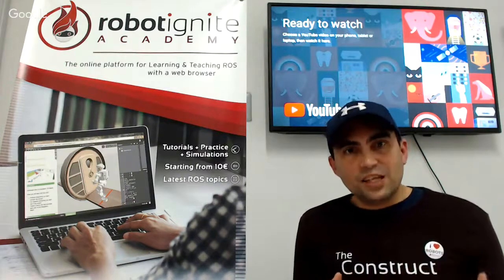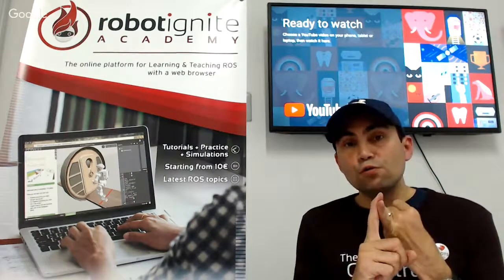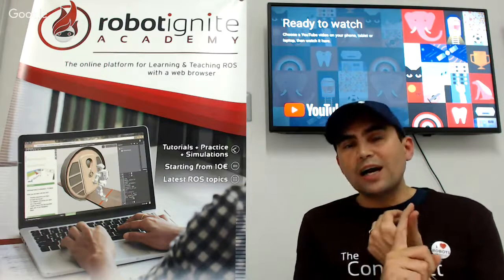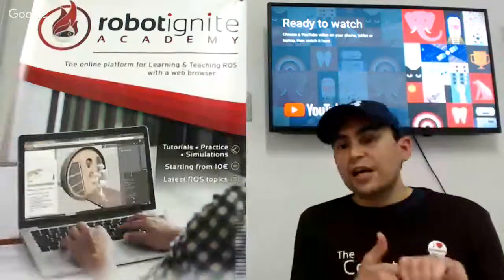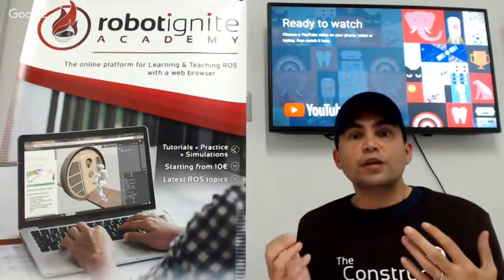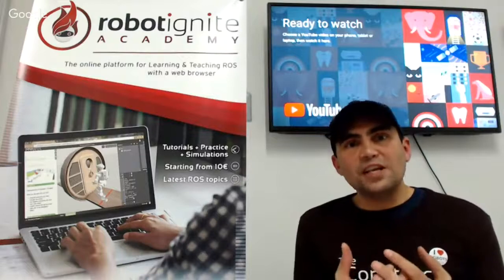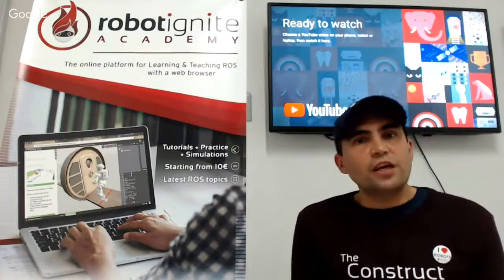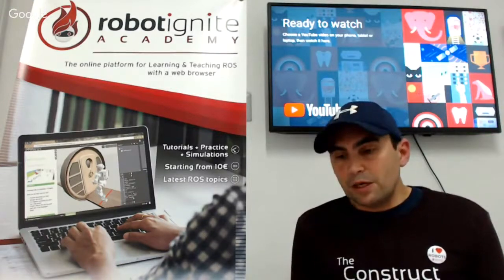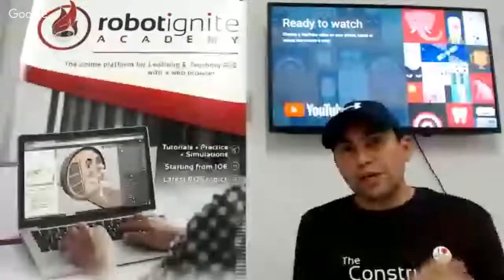In Gazebo, you have many types of sensors simulated, like IMUs, GPS, bumpers, sonars, point cloud devices, images, lasers, LiDARs, and many, many types. So you can simulate a sensor. You can even include the noise of the sensor in the simulation. So it's just a matter of putting in the effort. I don't know this specific sensor that you mentioned, but maybe you can approximate it with something that is already done.